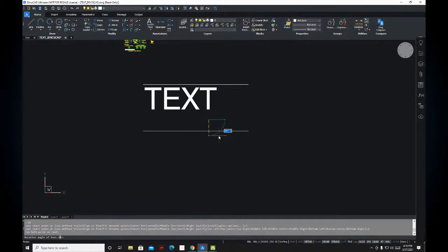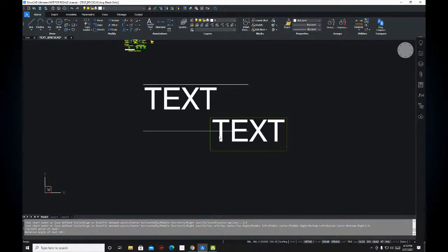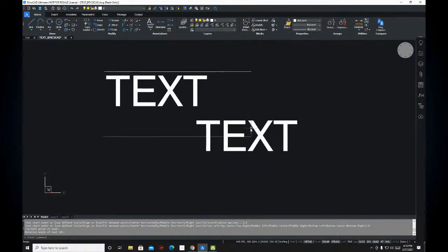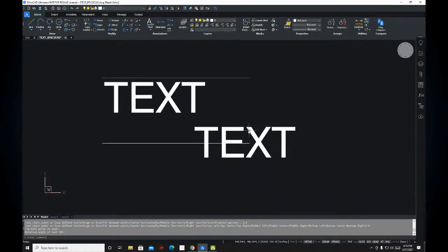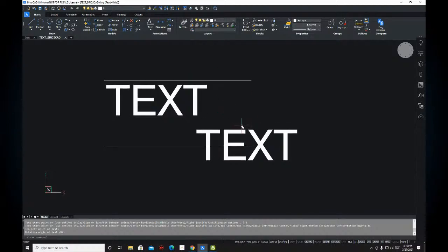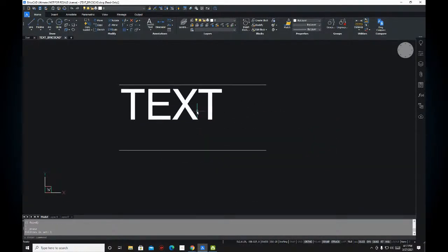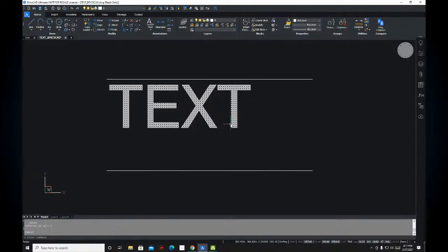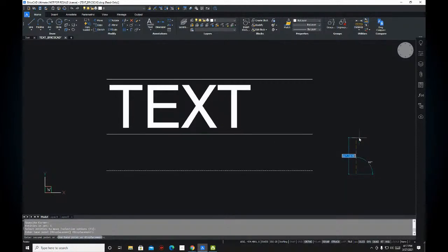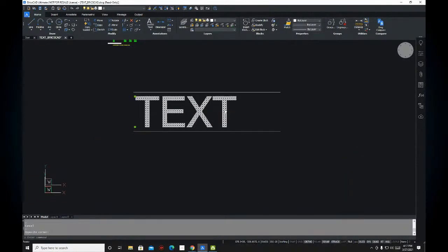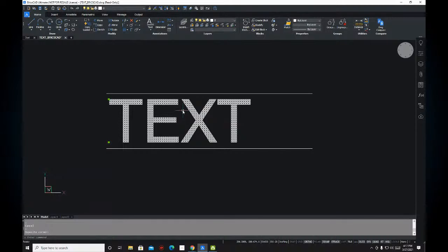If I'm going to click here, then accept, then type text, your text will be misoriented or not properly placed. Although you can still move this text if you want, it becomes a hassle in doing the project. So more likely the function of the justification is basically on how you are going to properly place your text.